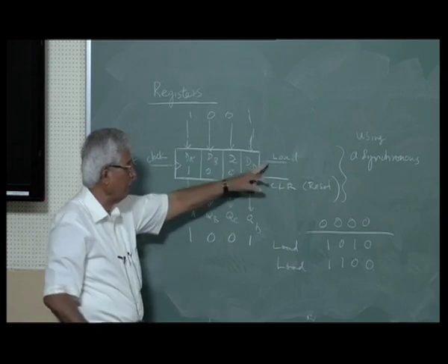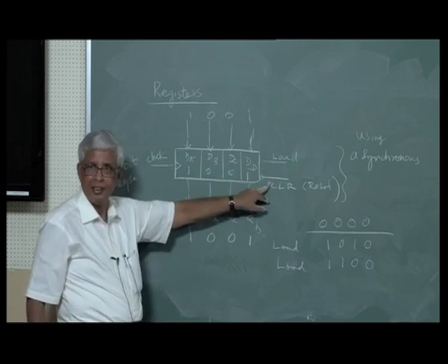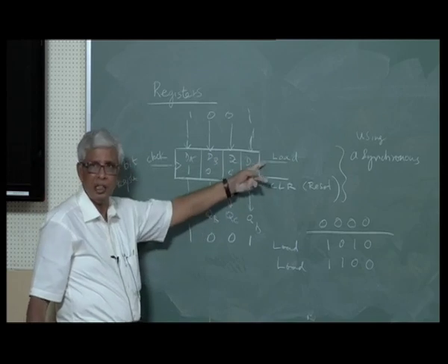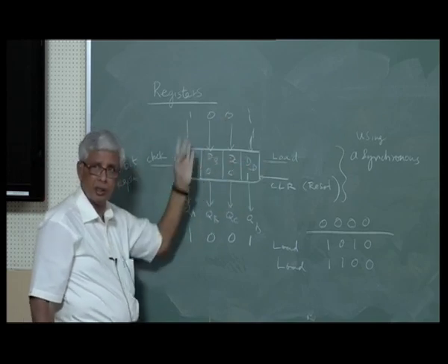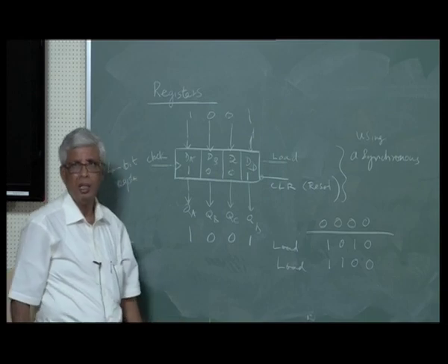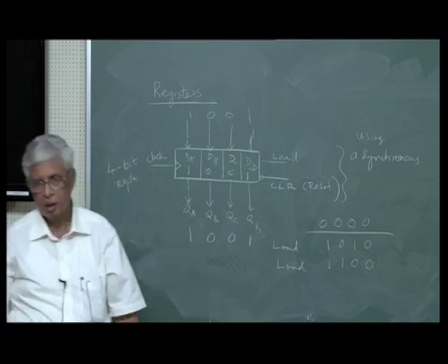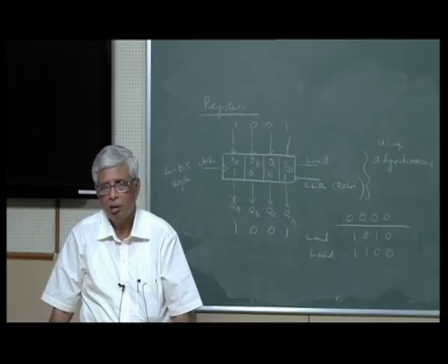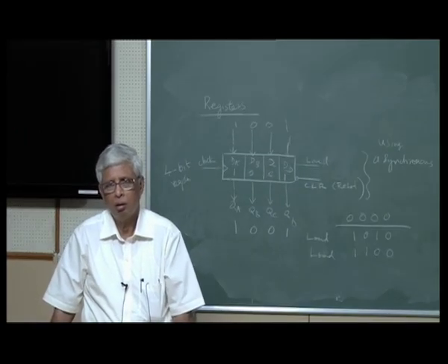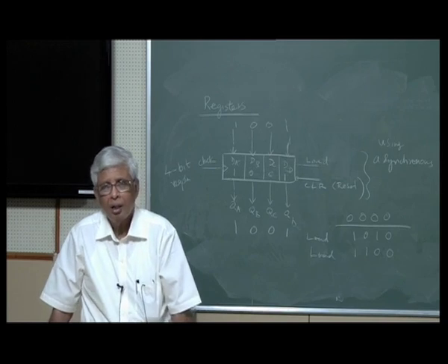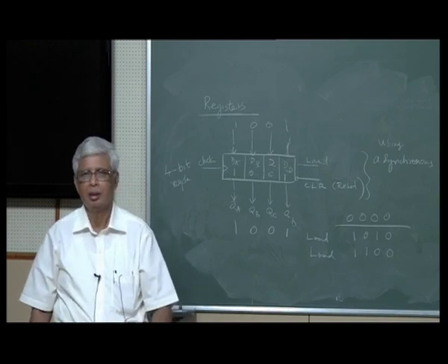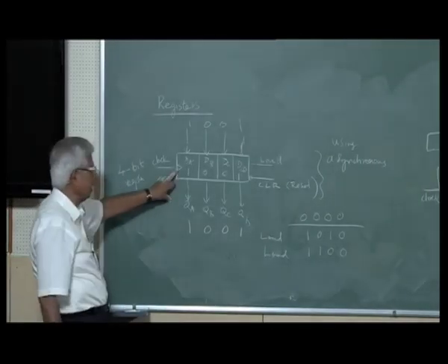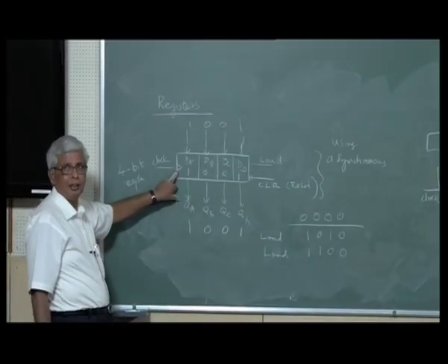So that is why I wrote this as asynchronous load. Anytime I want to load it, I can give the load signal, as well as put new values, and get it. Load is asynchronous. Okay. When the clock is high, and at that time the input is changed, then what will happen? Clock is high, input is changing, that is, I am changing the value. Then what will happen? What is the symbol?